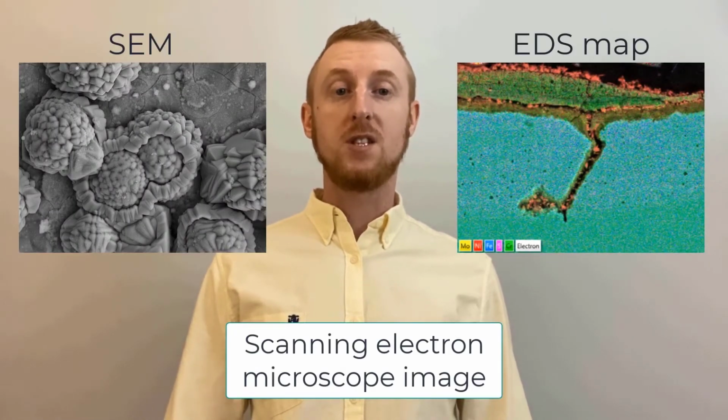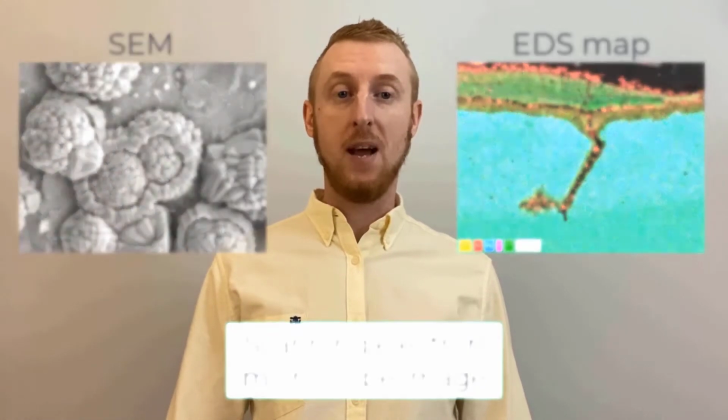As you may know, there are existing scientific approaches to study corrosion resistance of metals or alloys using standard electrochemical measurements, where we use standard 3-electrode liquid cells like this. After the electrochemical experiments, we often bring our samples to a microscopic lab for studying localized corrosion damages.